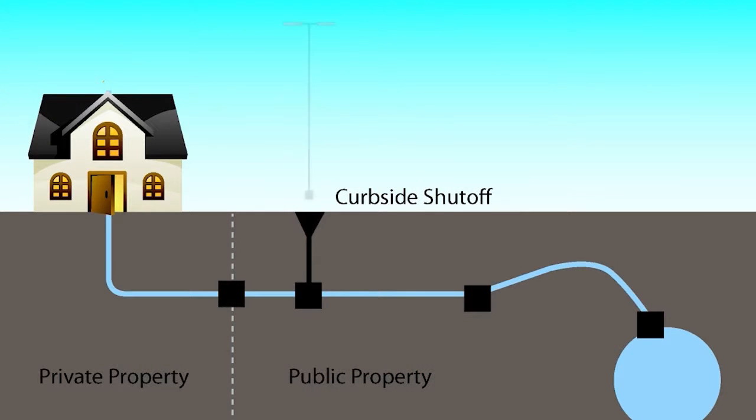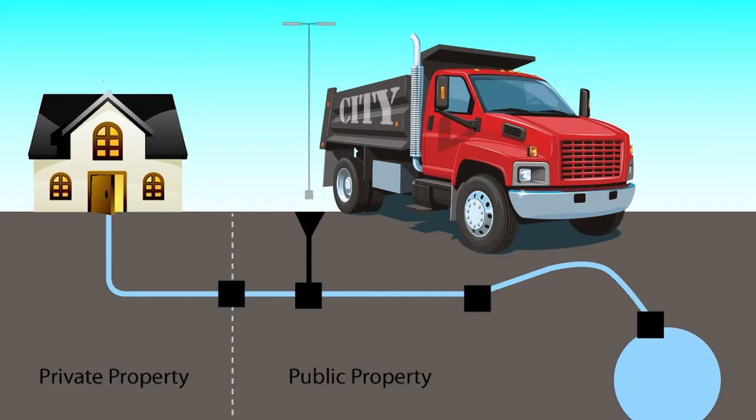Next, you will check that the water is turned off at the curb. If it is not, you must still complete the winterization. For pre-sale properties, provide a bid to shut the water off at the curb. You may also need to meet the city for curbside shutoff.